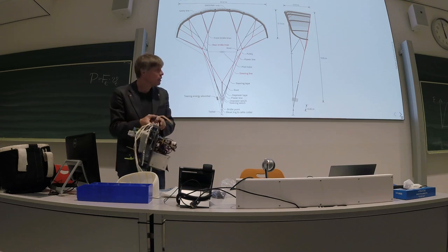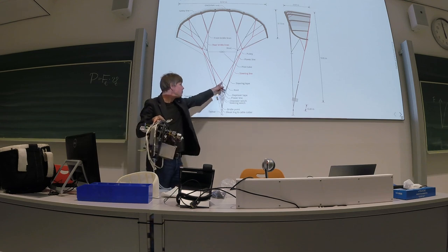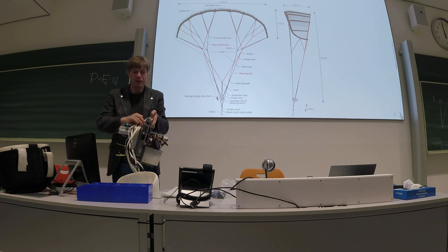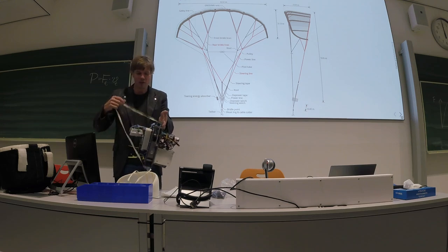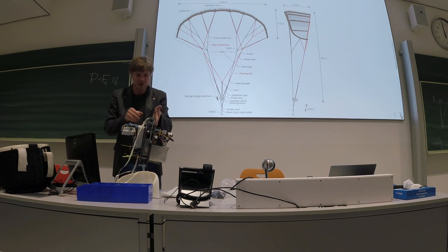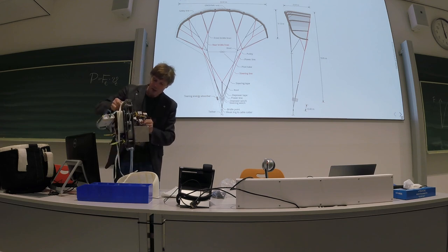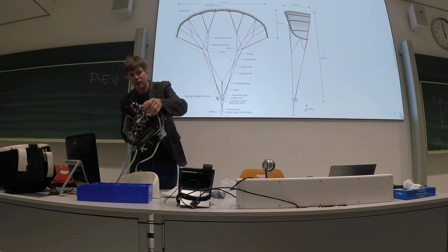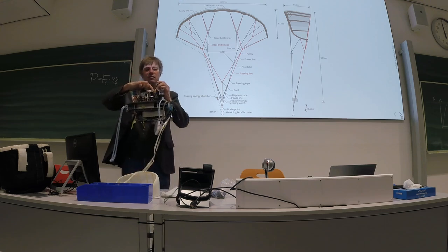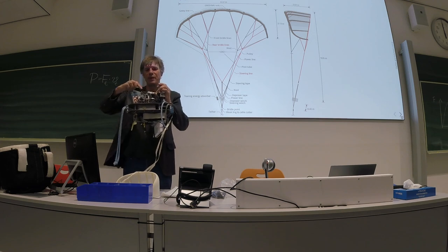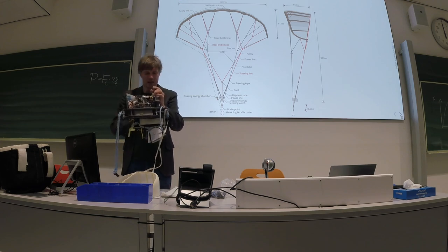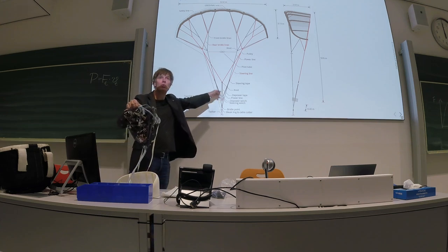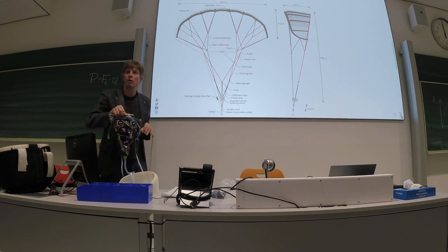For the reason that this power tape here always needs tension, we built in a brake. This is a small piston that can be actuated against the axis, and that reduces the force to a very low value when you don't move this tape.